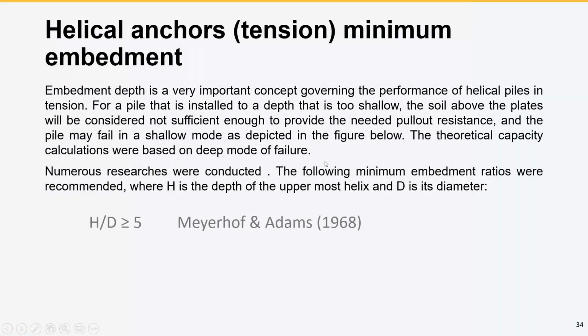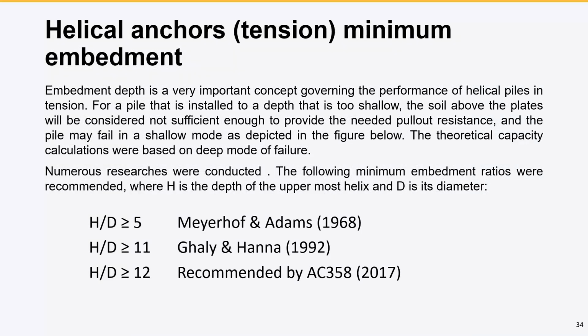Now, there is a concept, and that's the minimum embedment depth. The minimum embedment depth is a very important concept governing the performance of helical anchors. That means helical piles in tension, okay? Because if the helical plates are installed very shallow, the soil above that helical plate is insufficient to provide the pull-out pressure, and the failure mode will be shallow, okay?